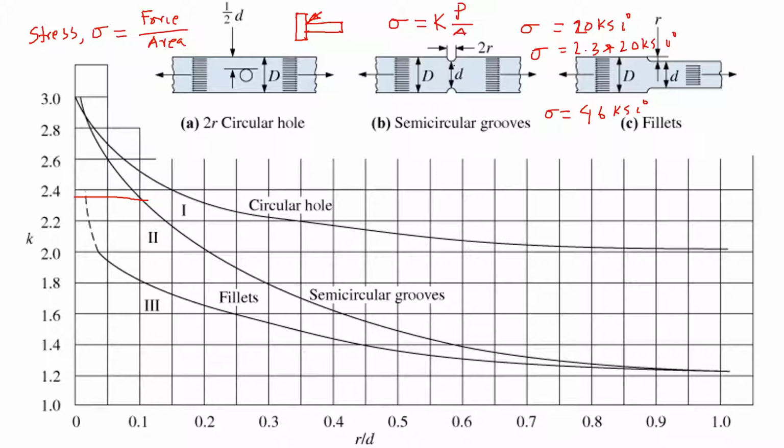If you have any sharp edge, corner, or radius, it is typically never recommended to have a sharp edge like that. However, for some situations we cannot avoid a joint, so we have to have some kind of fillet, some radius, smoother instead of a sharp corner.